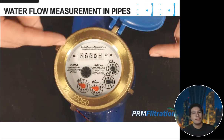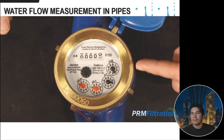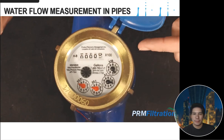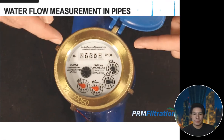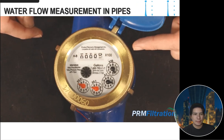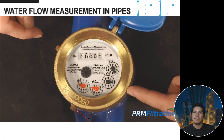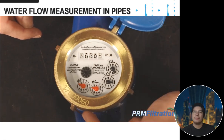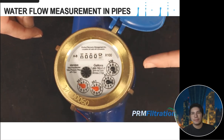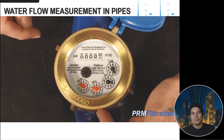When you are reading this meter, you're going to look at the counter, but you also want to look at each of the dials to give you an accurate picture of the amount of water that has run through your meter. For example, this meter has not run any 100 gallons through it, but has run 43.88 gallons through it. So that's on the 4, the 3, the 8, and the 8.